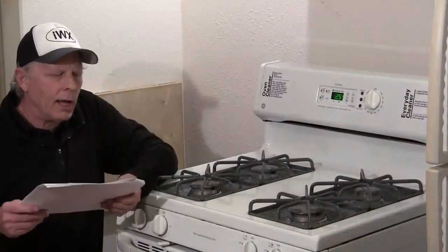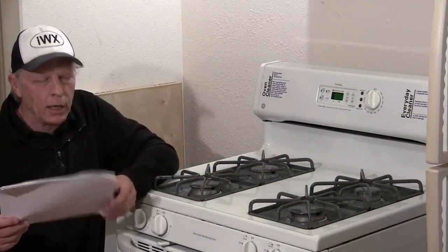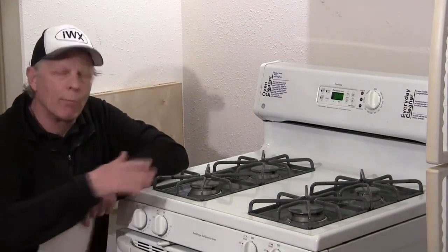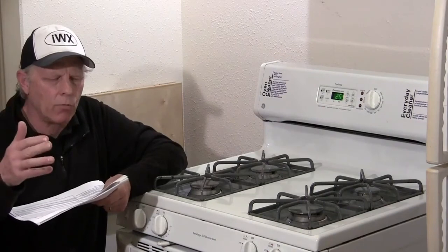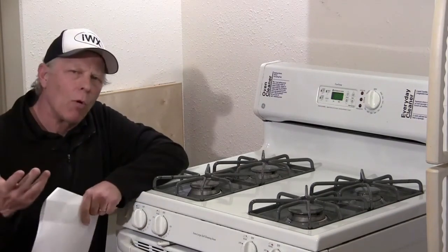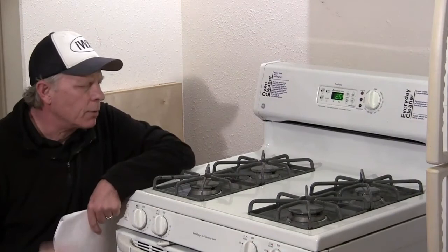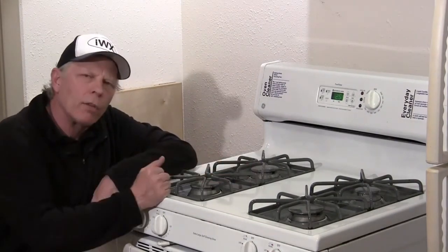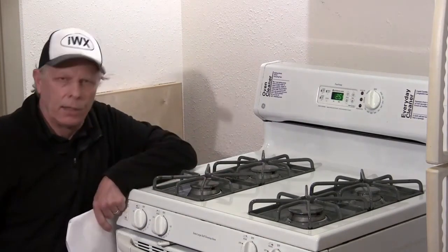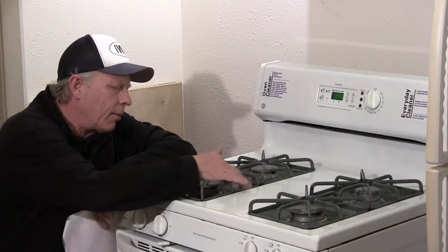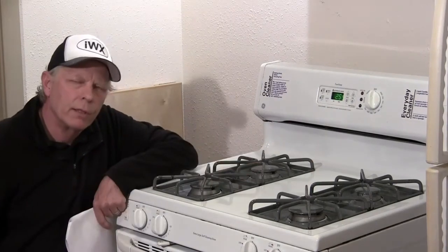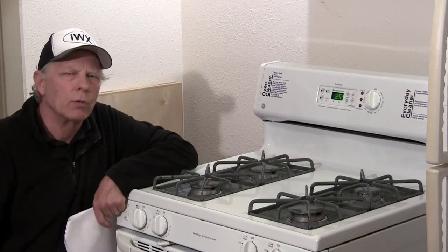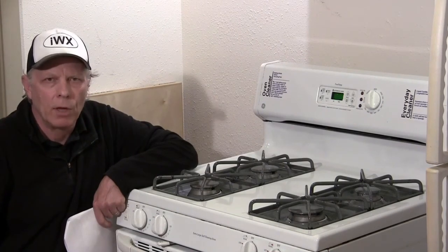Okay, we're on line 11, which is the last line, that last combustion safety item on the field guide, and it's about the stovetop burners. We're supposed to inspect the stovetop burners for flame quality. This is quite a subjective test, but generally what we're looking for is that the flame is complete all the way around the ring here, and that they light. If the flame is missing in places, then what you have is excess carbon monoxide production, which could be an issue for the ambient CO in the house.